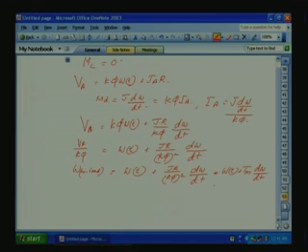So the solution will be omega t will be equal to omega 0 into 1 minus e raised to minus t by Tm. So this is the time constant. So this is called the electromechanical time constant. So let us introduce the electromechanical time constant into our system and then modify our equation.